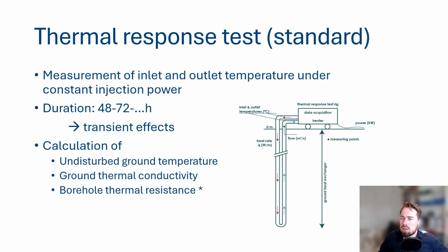So I call this the standard way of doing a thermal response test. It's basically just the measurement of the in and outlet temperature of a borehole under a constant injection power. So what we do is we basically drill a borehole with a ground heat exchanger, a grout, etc., like we would for the rest of your project. So it's basically a sample for your entire borefield.